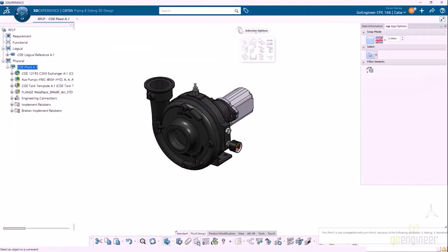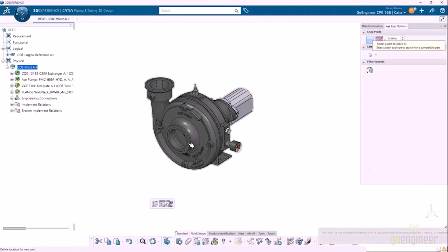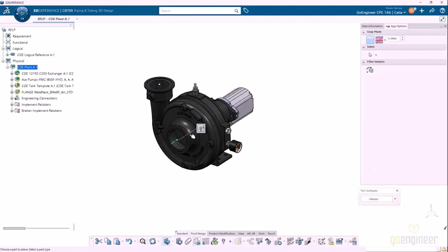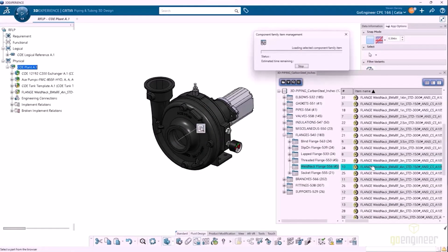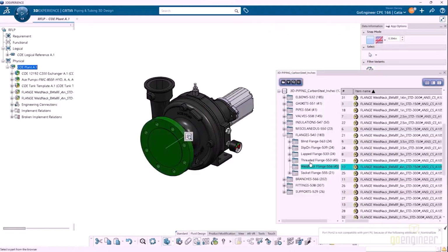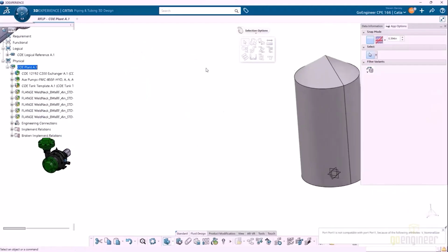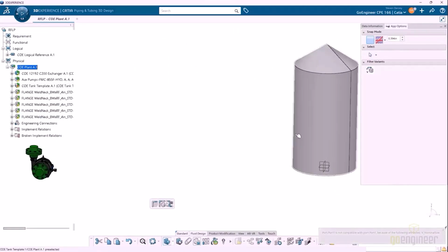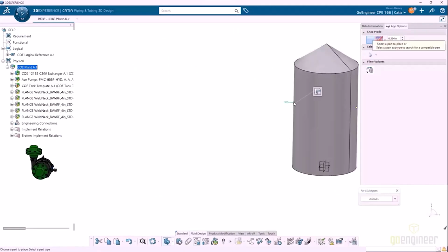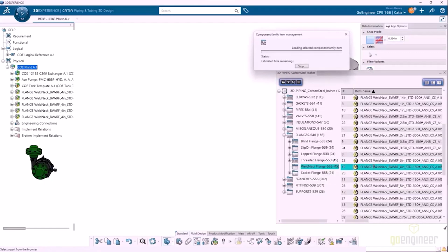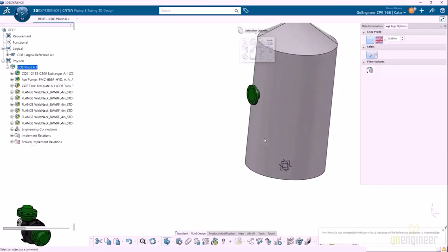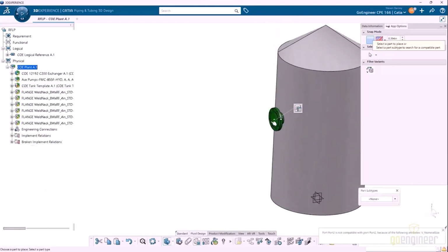And all of these are going to be 4-inch pipes. So same thing. Each of them have ports, and the ports know the orientation of that part. And in this case, we're putting double weld neck flanges on there. There we go. So that looks good. Same thing, this tank actually has 2 ports, one to the left, one to the right. So we're going to place one on the left part of the port, and then we'll double that one up as well.